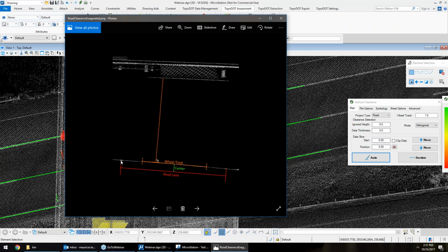And so you have to do it lane by lane, because super elevation lanes will change. You really want to know the elevation of the road where the wheels travel. That's actually going to define the super elevation of your road. You don't want to fit planes in small areas, because they can be really far off. You can get a rut, and the plane in a small area can be not even close to the gradient of the road. So this is the way it's done by lane. All you have to do is pull out those lane lines, select them, and say go find it. It does it lane by lane, so you'll see measurements in each lane.